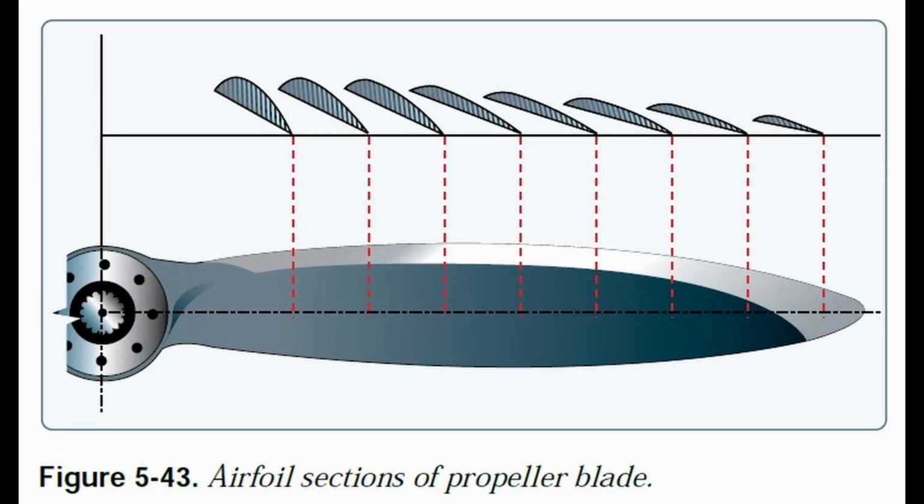As I've been mentioning, angle of attack of the propeller decreases with an increase in airspeed of the airplane. With the root of the propeller having a slower rotation velocity than the blade tips, washout, or that twist shape, is added to the propeller so that the blade angle of attack is more or less uniform at one specific airspeed and RPM combination. At this airspeed and RPM combination, maximum thrust efficiency is achieved.